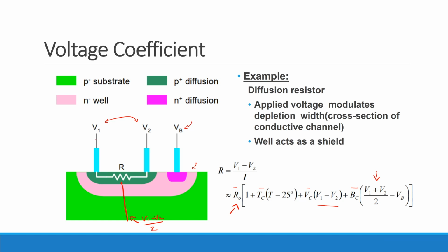Okay. So what you're saying is do something like that. Kinda. Yeah. So you're saying, okay, take V1 and tie it to the body over here. You could do that. Now notice, all you've really done in some sense is translate it so that V2 is controlling everything. So you now have VC plus VB over 2, right? So what you really want is to figure out what that center point really is and tie that to the body. So in principle you could try and do what I just drew there: tap the resistor in the center and draw a wire over. In practice, what you usually end up doing is building some sort of dummy circuit that tells you where that center point is supposed to be and then makes that tie.